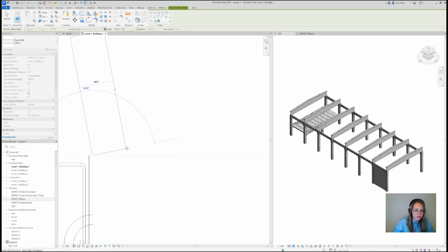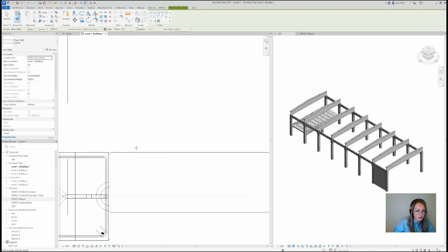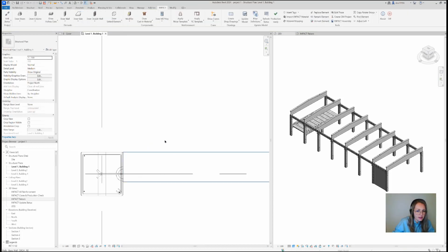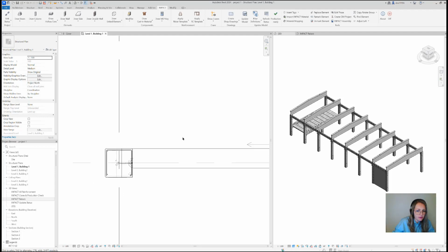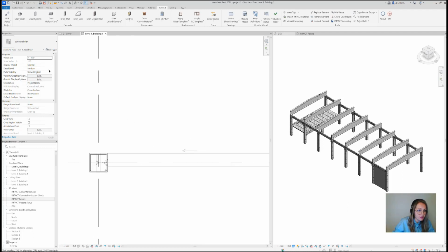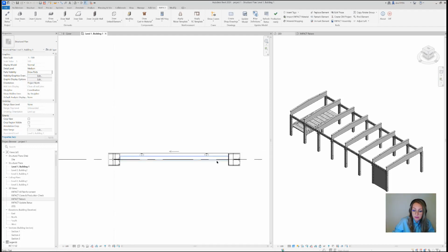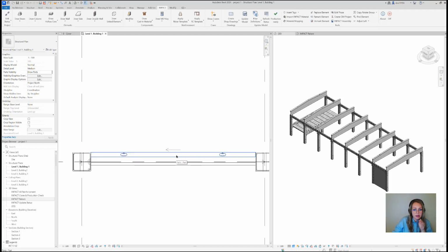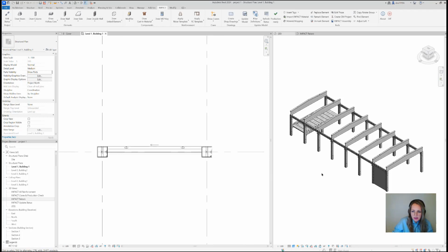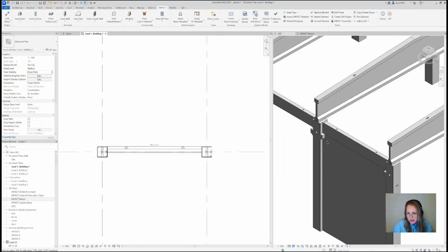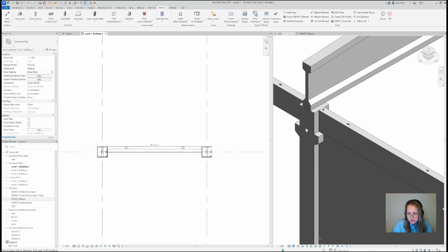the simple explanation is that the direction of the wall is what decides which side of the wall is going to be the load bearing panel. So if we go to parts now, we can see that because I draw the wall from right to left, I actually get the load bearing part where I want it. That's on the, so to say, inner side, right? So here on the 3D view, I can see I have some wall, and it looks like this.